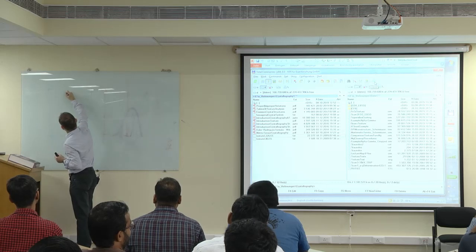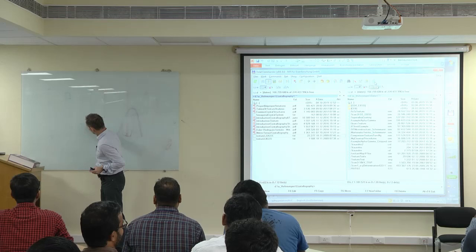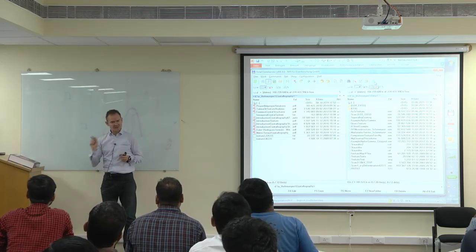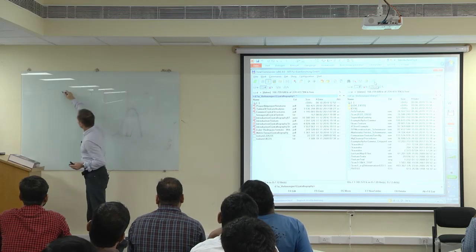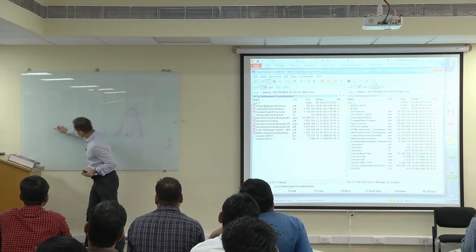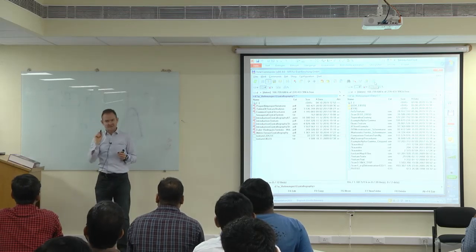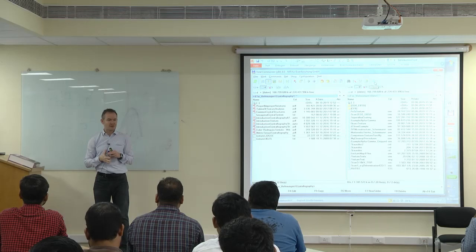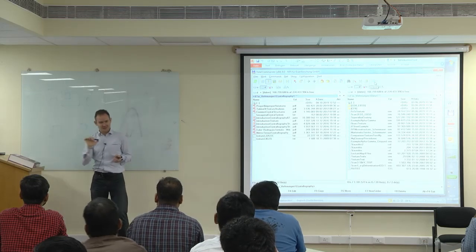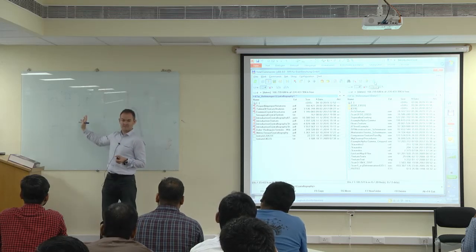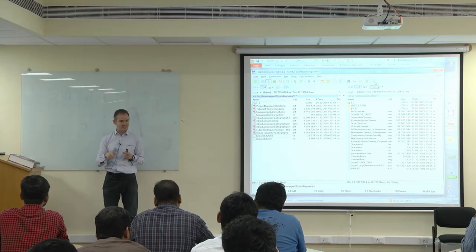Or, for example, if you have a sample and you have measured with EBSD just a little corner, and you get a nice texture out of it. Now go into another corner and measure again and see, is this texture identical? And if it's not, then you remember, okay, obviously I need to measure a larger area, or I need to measure at 4 different corners and add that together. So maybe not all of you are interested in getting a proper texture, but if you need that, then this is quite an important consideration. How do I sample my specimen in order to get proper data?